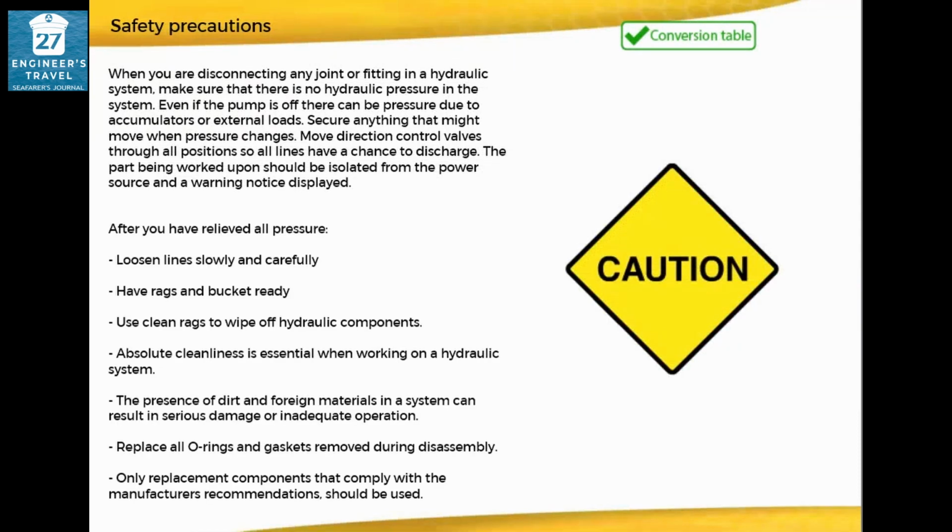After you have relieved all pressure, loosen lines slowly and carefully. Have rags and bucket ready. Use clean rags to wipe off hydraulic components. Absolute cleanliness is essential when working on a hydraulic system. The presence of dirt and foreign materials in a system can result in serious damage or inadequate operation.